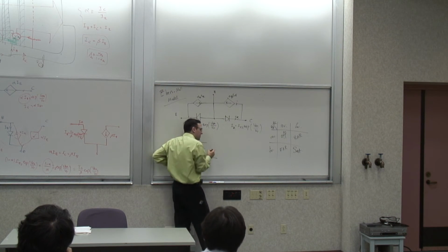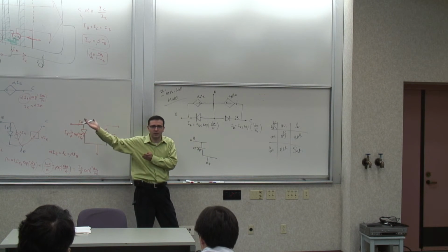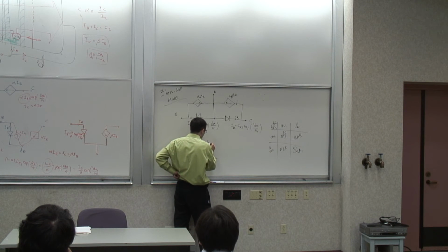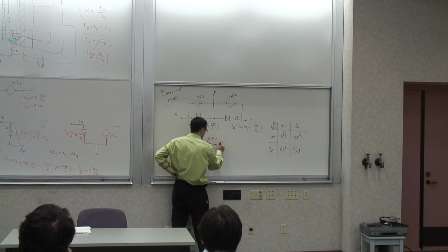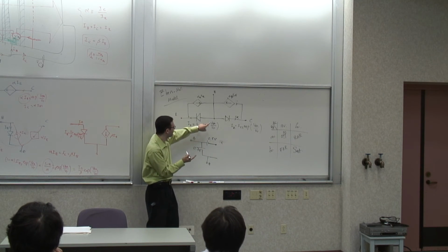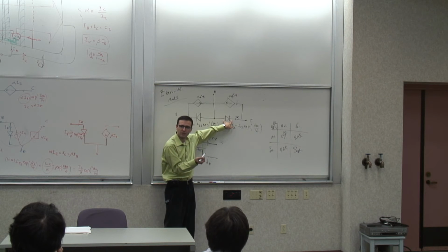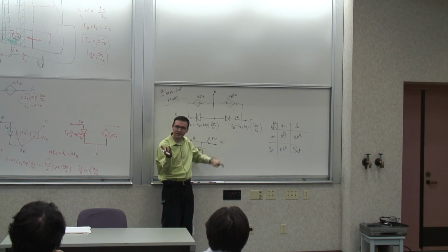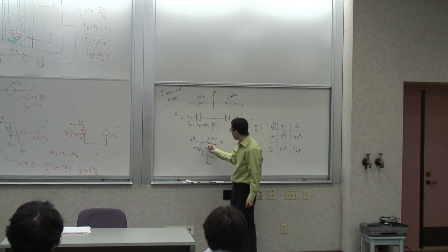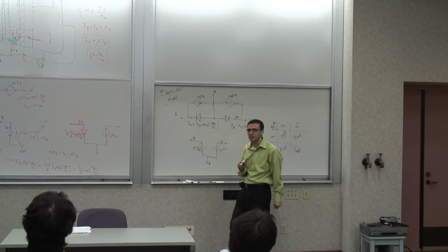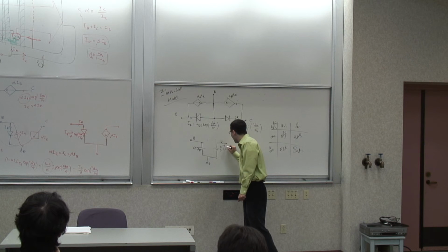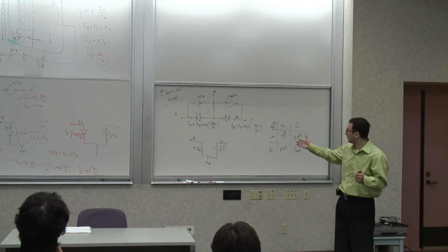When does that happen? Well, you need at least about 0.5, 0.6 to get to any reasonable level of current, right? So at that level, what you really have is something like this. So this is something like 0.5 volts drop to the collector. So this junction is forward biased by about 0.5 volts. That's the edge of just starting to carry some substantial current. Now, it's 0.7 up and 0.5 down, so I can redraw it equivalently as a battery of 0.1 to 0.2, in this case let's say 0.2 volts here. That's the way we approximate the transistor in many cases in the saturation region.